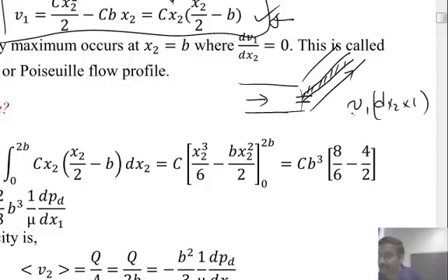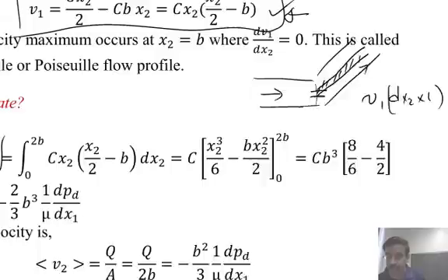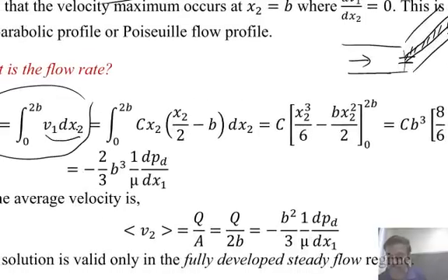So that is essentially velocity times the cross-sectional area, which gives you the volumetric flow rate. So that's how this v1 times dx2, then you integrate that because the velocity actually changes from point to point. The flow rate flowing in this section is going to be smaller than the flow rate flowing in the middle section. So we need to account for that and integrate.